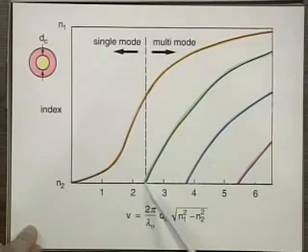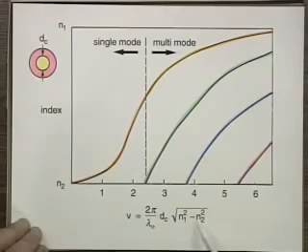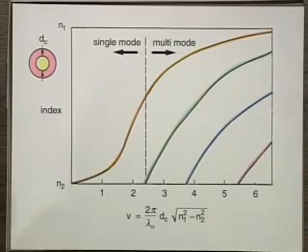In this previous demonstration, then, what we had was a single mode fiber, which means that's a fiber that satisfied this V number being less than 2.4 or so, because of the choice of the core diameter, the wavelength, and the difference in the indices. Now, in this next demonstration, we're going to violate this. We're going to create a V that is bigger than this value.